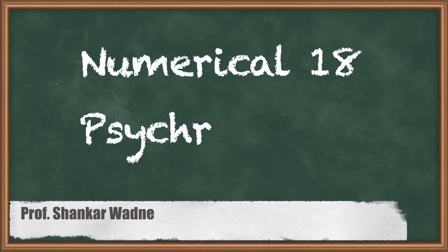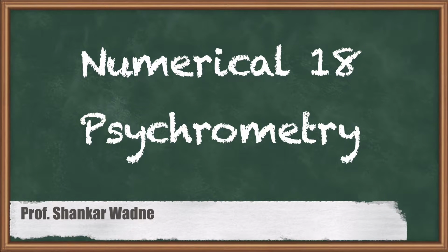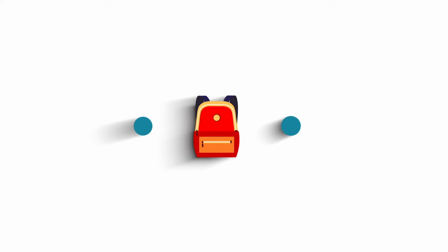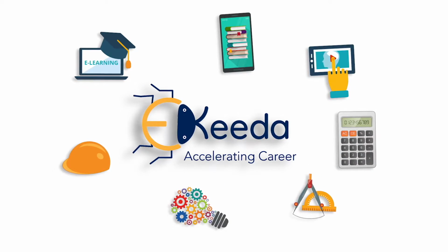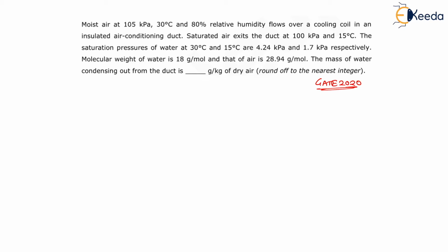Hello my dear students, in this lecture we are going to see one previous year GATE numerical. This question was asked in GATE 2020 for 2 marks on psychrometry. The question is, moist air at 105 kilopascal, 30 degrees Celsius and 80% relative humidity.